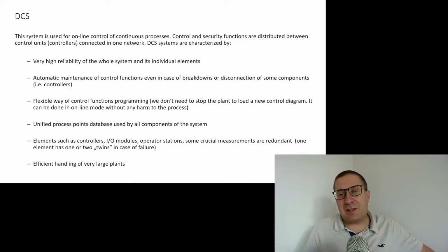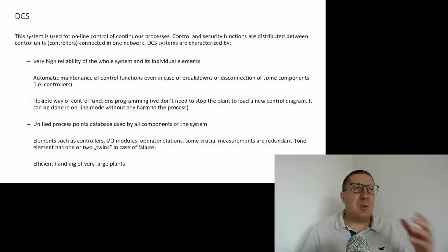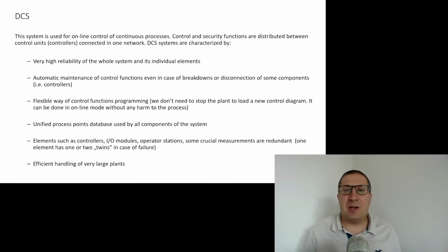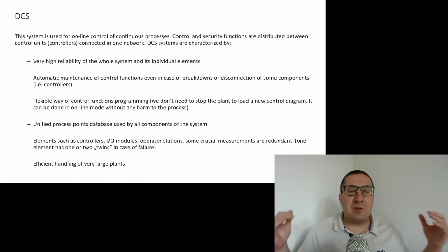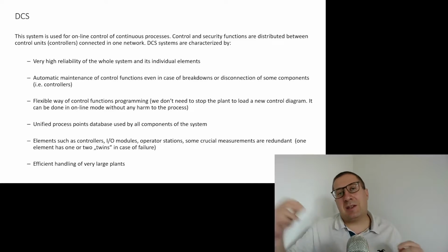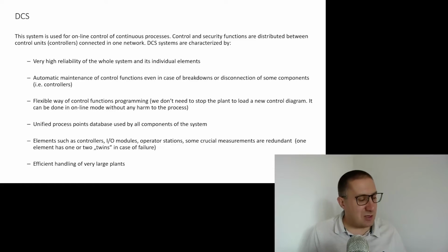In the case of heavy industry, you really have to play with the process all the time. You have to tune it here, tune it there, reduce some trends here and there. Maybe the temperatures are too high somewhere, so you have to act. You have to reduce the set point for this temperature, or open some kind of cooling water valves. Maybe the pressures are too low, so you need to close the valve somewhere. So you have to dance with the process using the DCS.